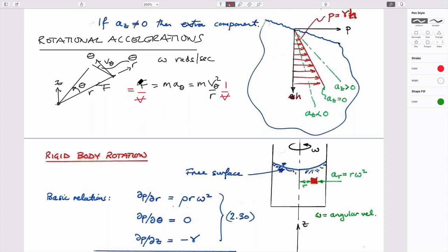Then we said that by definition, this is the units of dp dz. And in our particular case, this is just going to be change in pressure with radius. And we can write this, as you'll see written below, as change in pressure with radius equal to rho. So mass divided by volume is just density, and v squared over r.